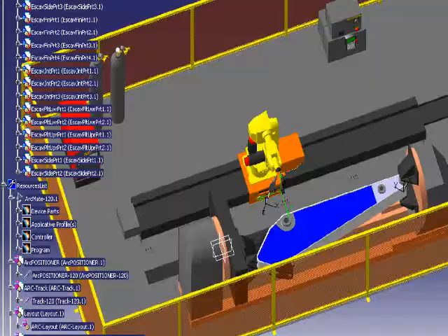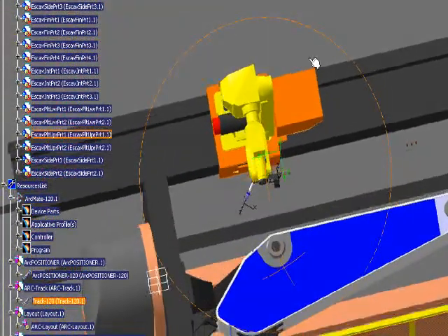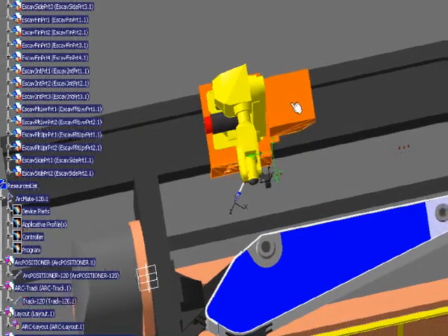Robotic arc welding cells can have a gantry or a part positioner, and sometimes both, and this helps with the flexibility of the work cell. It also lets the robot create a variety of welds. Starting with a completed layout, the first thing to do is mount a robot to the gantry. We're using a robot from the robot library in the software.